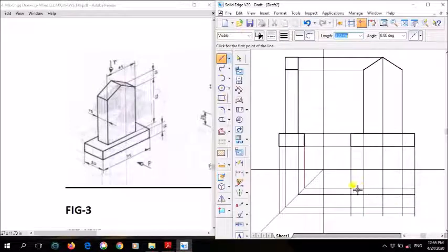This is the outer base, that is 75 by 30, and this is the inner one, that is 45, and these two faces are divided here. These two faces are divided. Once you have drawn these extension lines, using a thick line, you go from here to here.